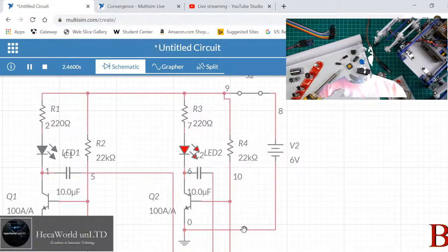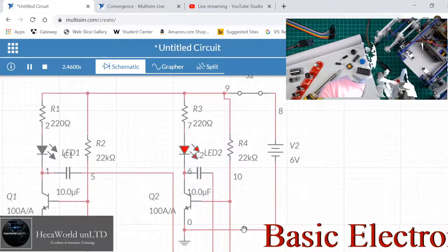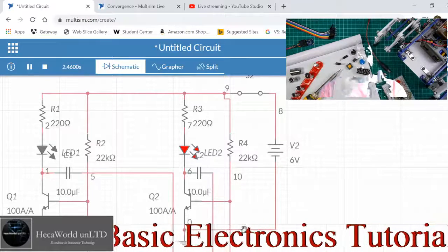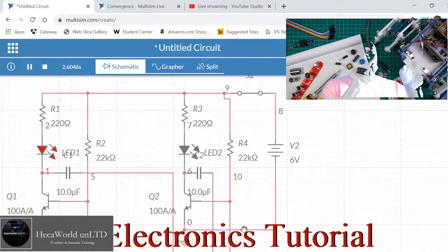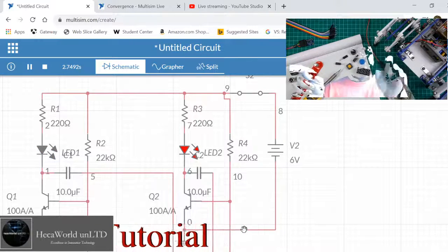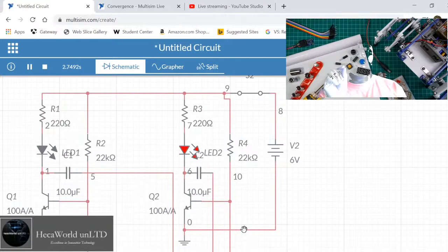When you do that, you ensure that maybe two will be on at the same time and one will be off. And then when that one comes on, the next one will be off. So it's gonna go off, on, on, then on, off, on, and then on, on, off, and it loops back. So it will be chasing. You can build a light chaser, right? If the T is small, it will look like a light chaser, where the off is running around in circles.